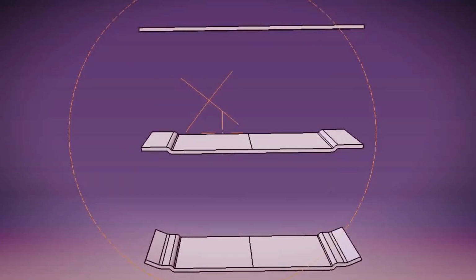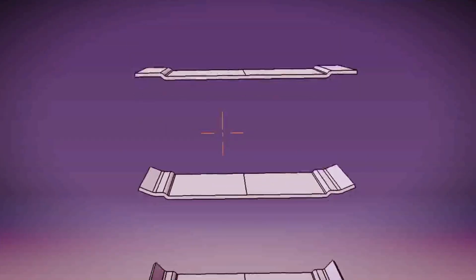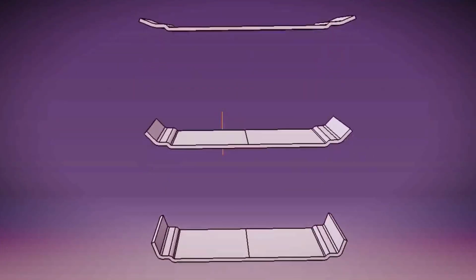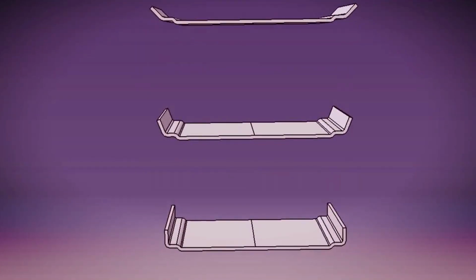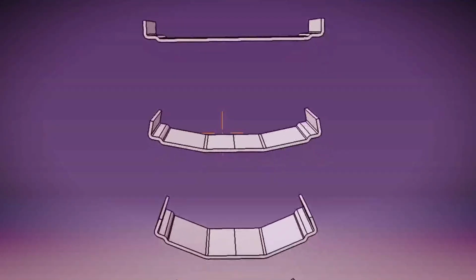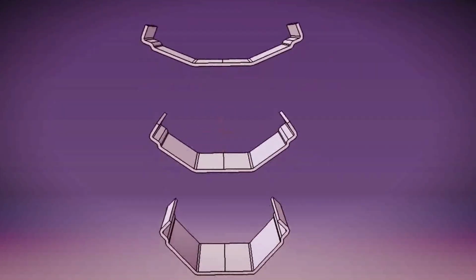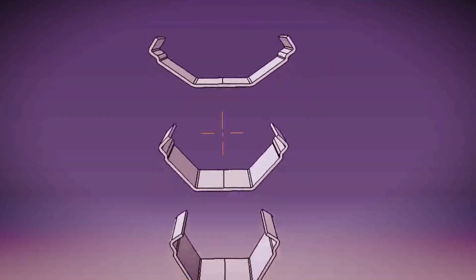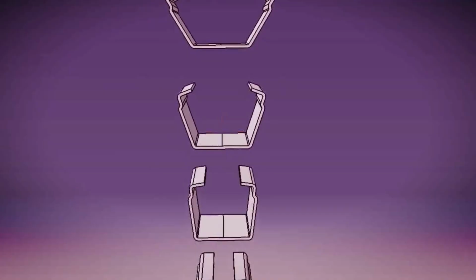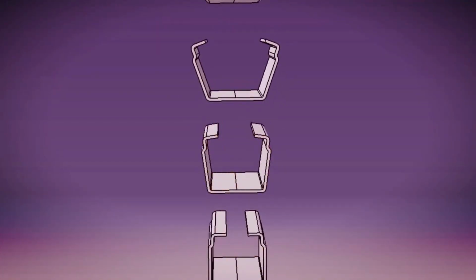But not all corners must be bent in turn. Often, 2 corners are bent at once if this is possible. Again, the designer decides this. That is, you see what an important role the designer has, who calculates the profiling. You can get an ideal machine from the point of view of mechanical engineering, but if the profiling is calculated incorrectly, then there will be problems with rolling the strip.